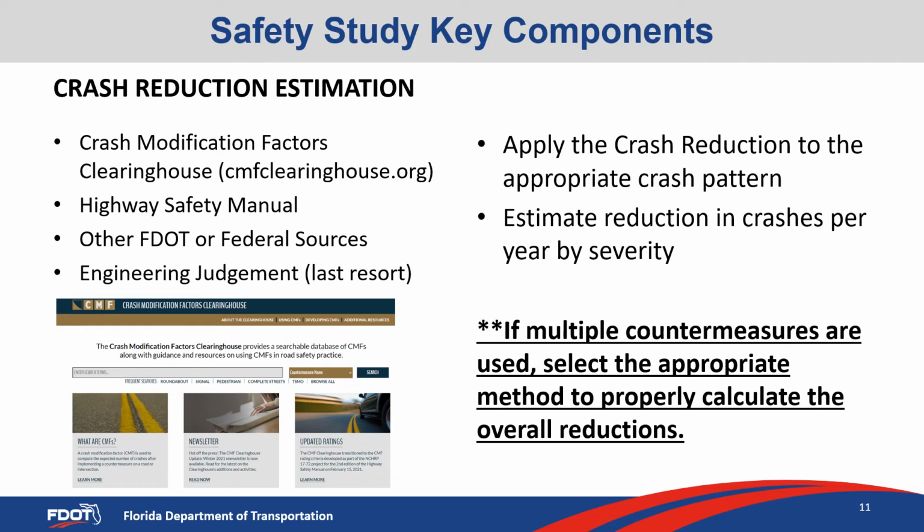And this should be a last resort after attempting to find documented acceptable crash reduction factors for the particular mitigation factor. Apply the crash reduction to the appropriate crash pattern. This is important. Many crash reduction factors focus on a particular type of crash or severity of crash, etc. So make sure you review the documentation and you apply the crash reduction or crash modification factors appropriately to the crash pattern that is documented for mitigation.